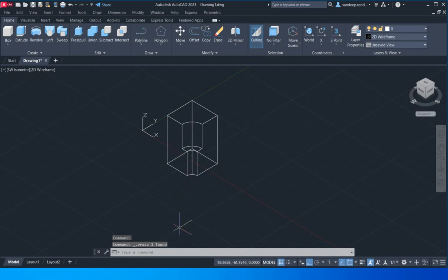So now I have two sides which I need to hatch. Firstly, the side I need to hatch is parallel to the XZ plane. The other side is parallel to the YZ plane. So before I even start hatching, I will have to again reorient my UCS. So I will bring it here. That's X, and I'll make that Y. Okay, starting off with my hatch command.